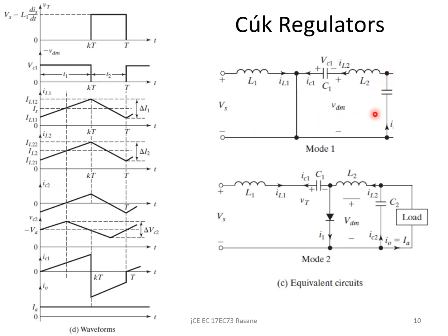The next waveform is the capacitor current IC2. So IC2 is this capacitor during the mode 1. You know that C1 is discharging through this, right? So you will see that the current through the capacitor is shown in this direction, so it will be in the positive. So for the capacitor IC2, it is going to be initially from negative, right? Then it will rise and reach the positive. So it is the same current that is flowing through the inductor and through the capacitor C1 as well. But you will note that IC2 will have both polarities, positive and negative.